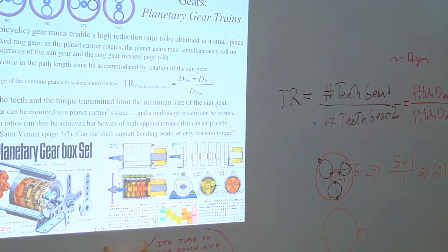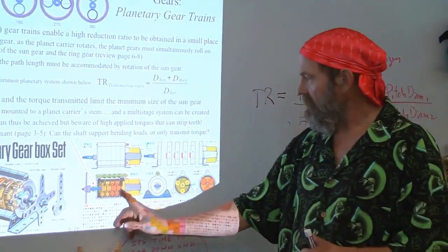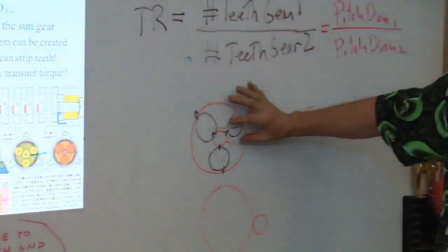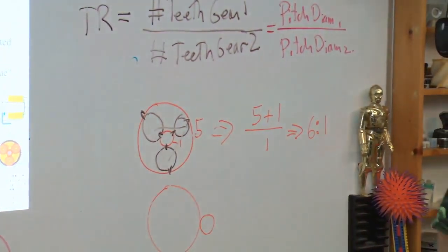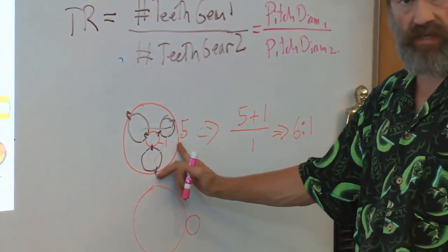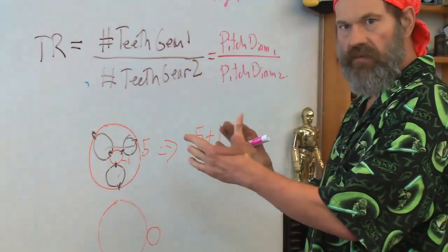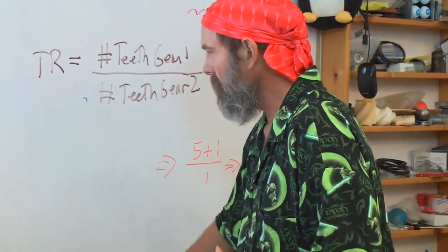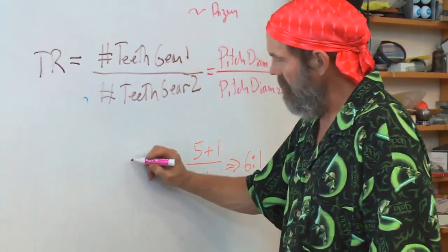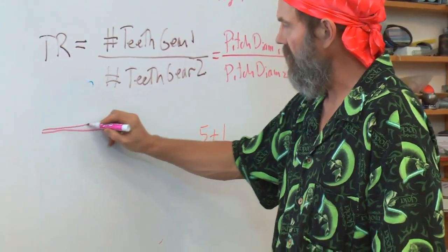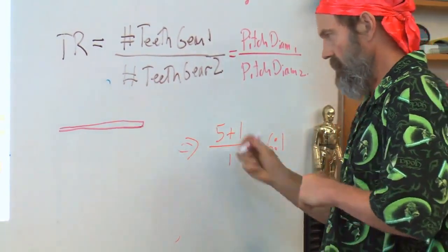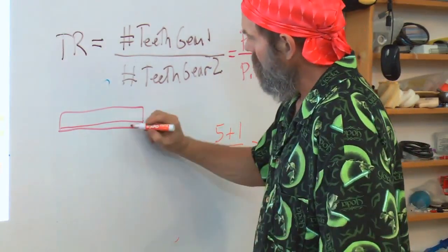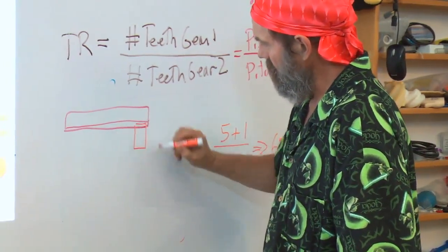With a planetary system, you can literally take stages such that the planet carrier, if I, in this case, have all the ring gears in a line, and they can even be extruded or formed all at once in an outer housing. And what you get is, here are the gear teeth of the outer housing. And then here is a planet gear.